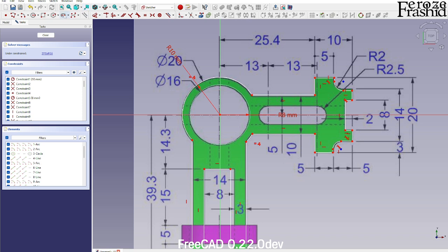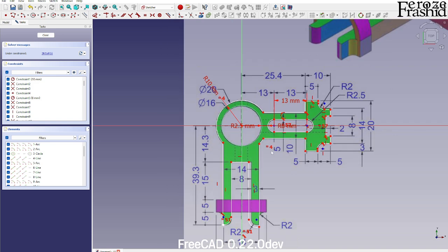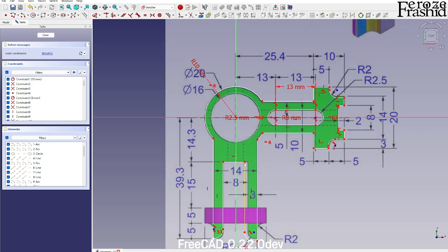And then I want to draw a slot. So here, I want to take this slot on here, and that length is 13. And then the radius, okay, I will place it on this axis, and then the radius is 2.5. Okay. So all we have to do is fix some of the dimensions, and then I'll be right back to you.